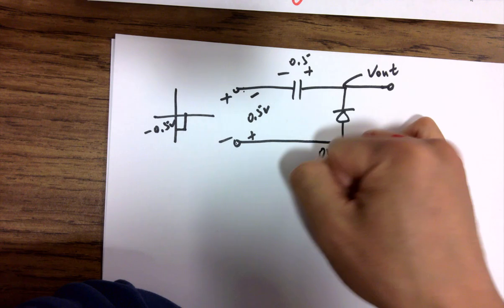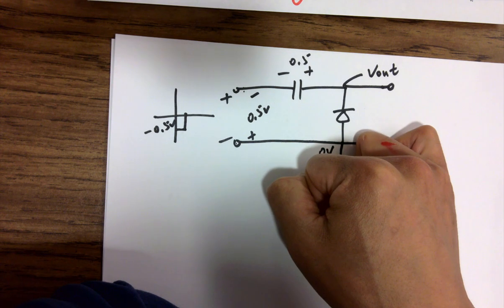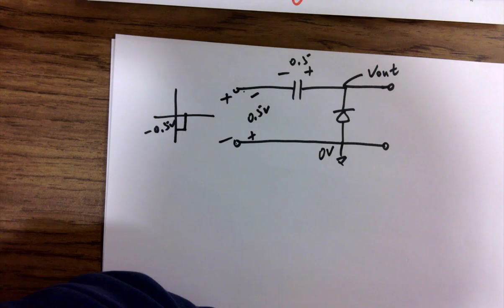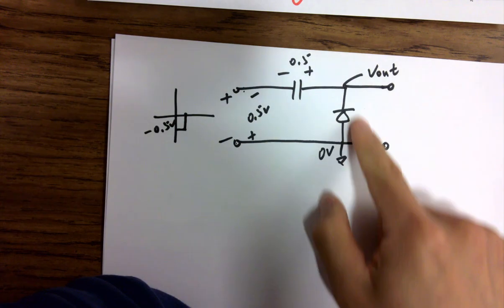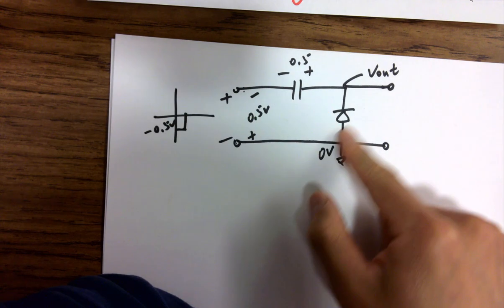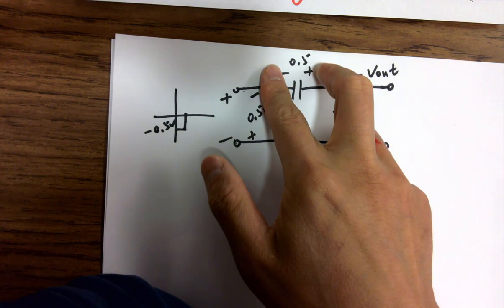So yes, if I'm understanding this correctly, V out is 0 because the voltage is negative, and therefore the charge can't dissipate to ground through the diode. Otherwise, wouldn't it be the voltage across the diode? Because it has to go through the diode to charge the capacitor. It goes this way to charge up the cap, and it stays.